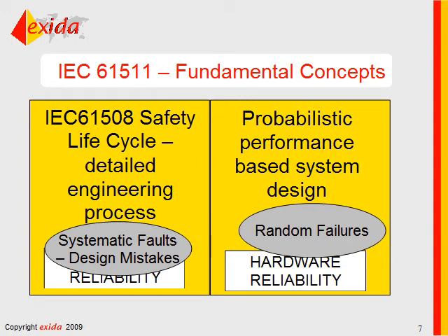The beauty of the concept of performance-based design is that you can implement whatever you want for your safety instrumented system, as long as you can demonstrate by means of probabilistic calculations that your solutions are safe enough. The disadvantage is that the standards don't tell you what to do.